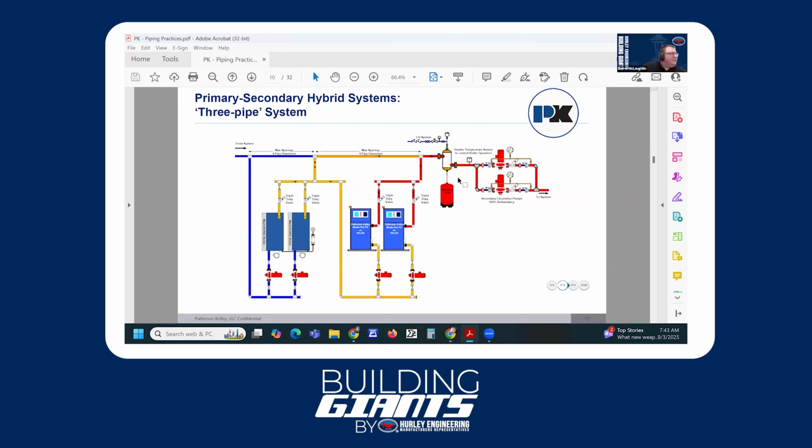So now you can see we've added two boilers. And we bring this up because one of the other benefits is, everything is associated with the cost. Traditionally, and still to this day, condensing boilers are going to be at a higher price point than non-condensing boilers. So maybe the people we're working with don't have the budget to replace all of them with condensing boilers, but they can do two. Well, we can still give them a system that gives them much improved efficiency for 75, 80% of the year. And then there's only 20% of the time that they might have to run some of these non-condensing appliances.